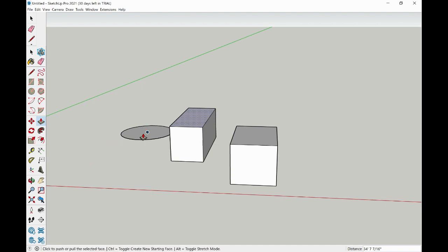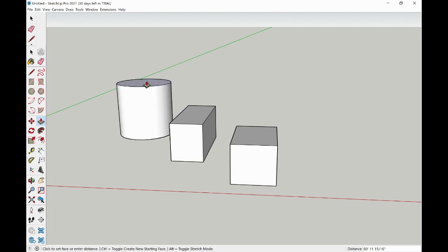With a circle, you can do the same thing. You can hover over it, seeing that we are in the command, and left click to begin to work it up. But you don't have to release and click to the size that you want. You can go ahead and type in a distance of measurement that you like. Let's say we wanted this to be 4 feet. I'm going to press enter and it snaps right to 4 feet.